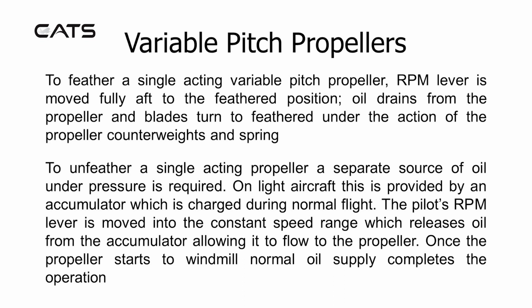To feather a single-acting variable pitch propeller, the RPM lever is moved fully aft to the feather position. Oil drains from the propeller and blades turn to the feathered state under the action of the propeller counterweights and spring. To unfeather a single-acting propeller, a separate source of oil under pressure is required.